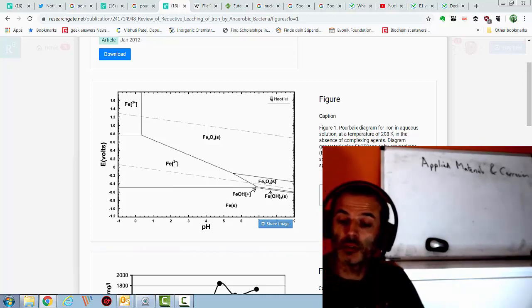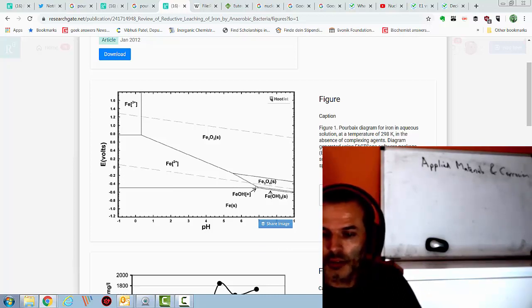And that is one of the reasons why ships and things that sink to the bottom of the sea last a surprisingly large amount of time. Instead of corroding to form the normal type of rust, Fe2O3, which is not very protective, it forms better types of rust like iron hydroxide and iron magnetite, Fe3O4, which are much better at preventing the metal from corroding. It doesn't stop it forever, as you can see, because the immunity line is still below it, but it does